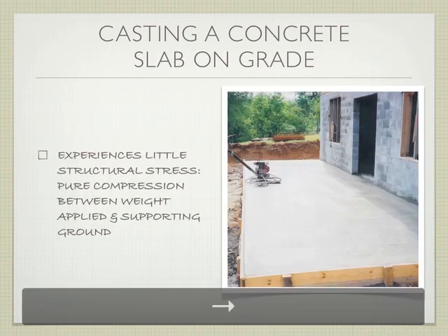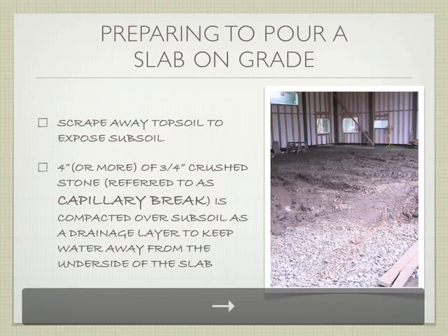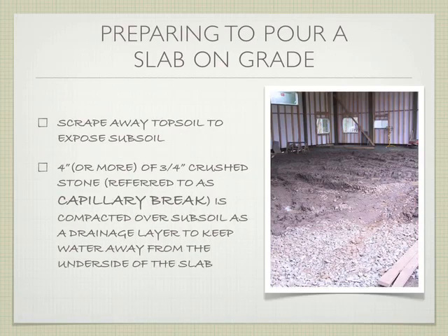But it's a pretty inexpensive building method, primarily because it experiences almost entirely compression, right? It's not spanning anything. If you stand on this slab, or you sit on this slab right now, all of your weight is going directly down onto the concrete, and all of that weight is traveling through the concrete and onto the ground that's below, right? So it's not really spanning anything. It doesn't involve a lot of complicated structural pieces. It's relatively simple, okay? No surprise, we use it very frequently on job sites, certainly in the state of California.